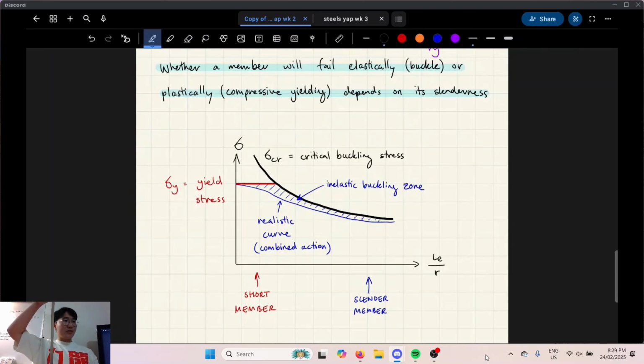It would be pretty strong in compression. You could use that as a table leg. However, if it's thin in one direction, it's not going to utilize the entire material in the stronger direction, because it's going to fail in the weaker direction first. That's what's happening with buckling.